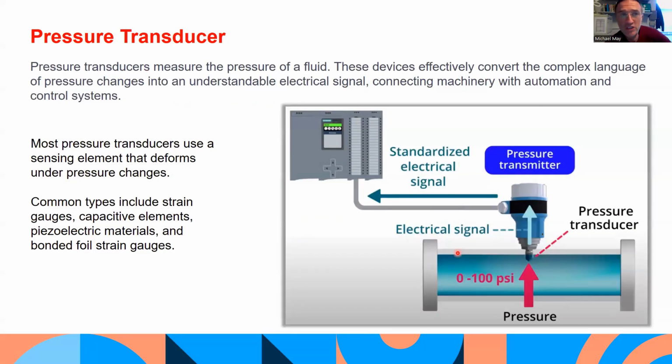You also have pressure transducers, which are basically screwed onto the system. The hole might be tapped into a pipeline, for example, and screwed in there. It may not give a reading directly on the pressure transducer itself, but the signal will be electrically transmitted through a control panel. On the control panel, the pressure value might be displayed, or it might be used to open and close valves in the system to provide a bit of control on the system.